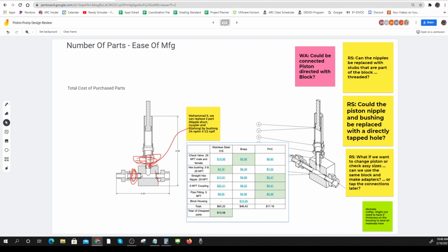So I don't think that I've got too much if I'm making all these parts or buying all these parts. What's expensive is if I want to have this stub sticking out and I thread it. That would be expensive. So I think this concept of just punching the holes through and threading them at whatever size your design is probably the cheapest.